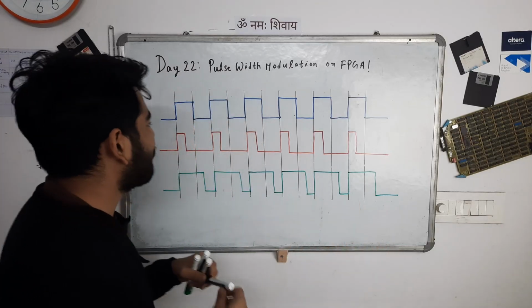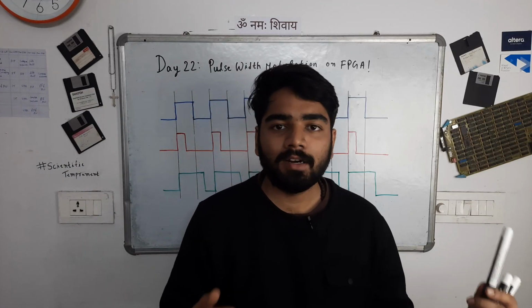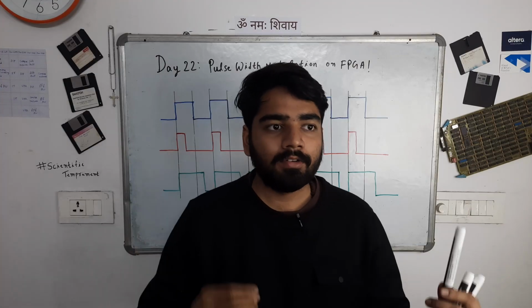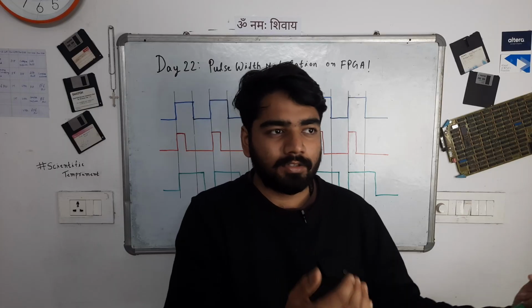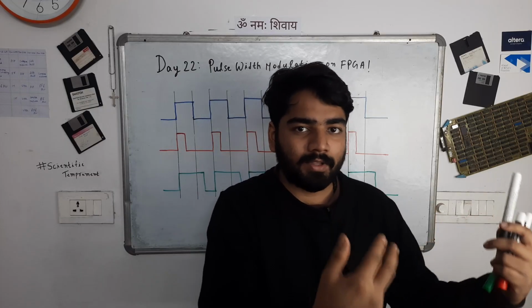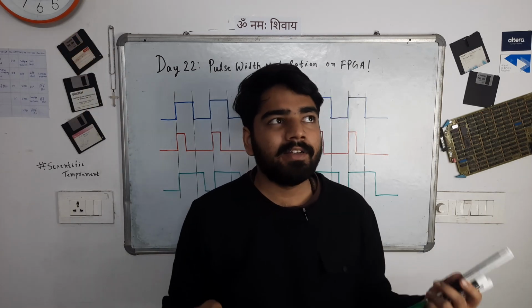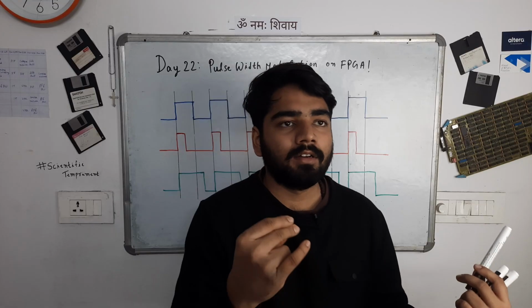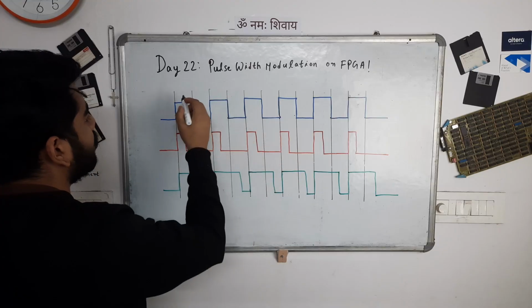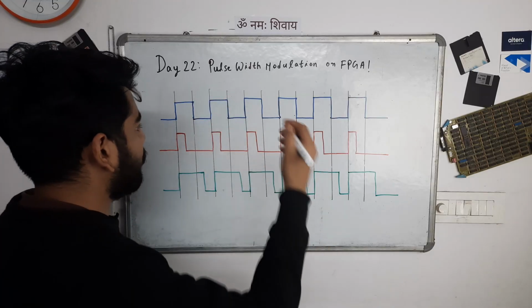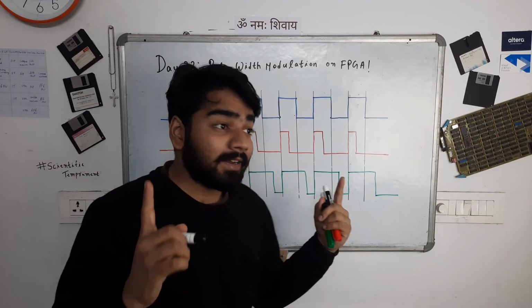What that means is that till now we have seen only square waves. When we were toggling the LED in previous videos, we were generating square waves, right? We used counters to slow down the faster clock, for toggling the LED after a certain number of original FPGA clock cycles. That generated a square wave because we were toggling the LED in equal periods of time. We were flipping the LED on for 1 second, off for 1 second, on for 1 second, off for 1 second, which means the on period and the off period were exactly the same, and that will produce a square wave.